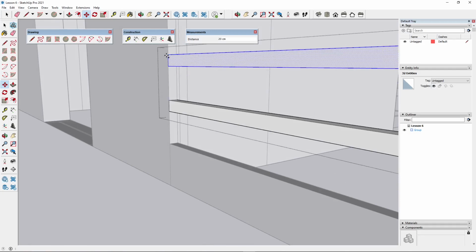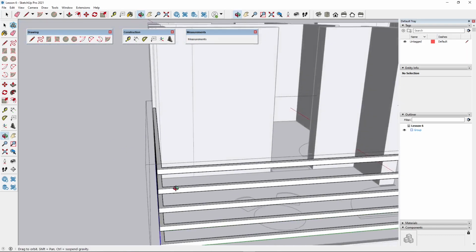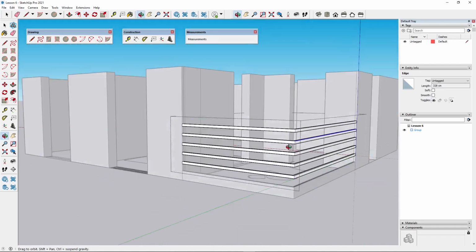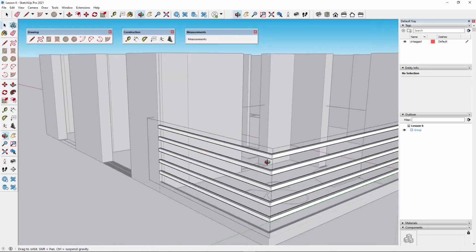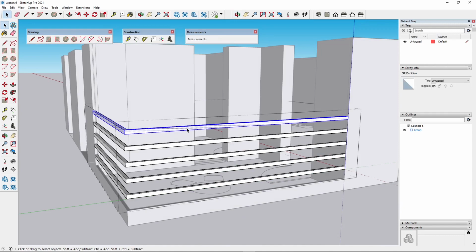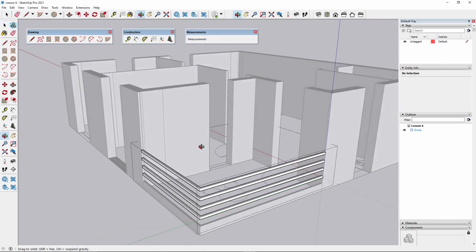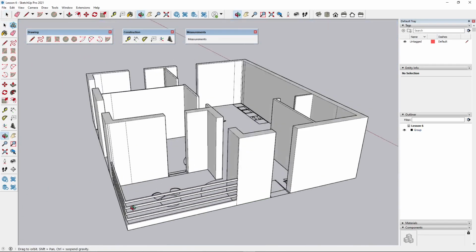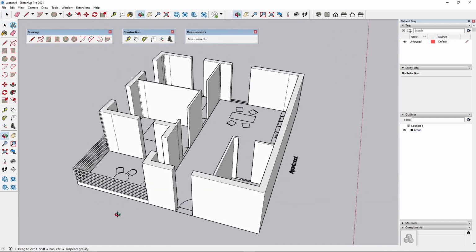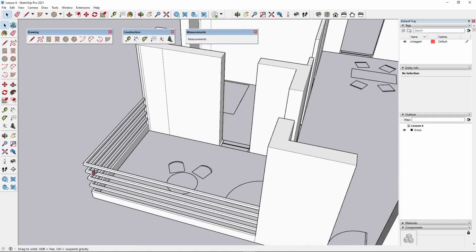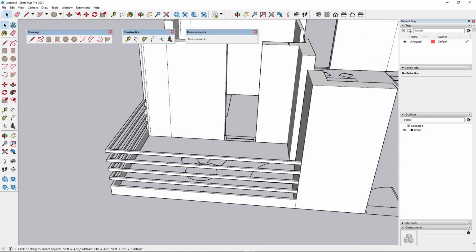Okay, and then click. And then to create more copies, I need to type, for example, 4, if I want 4 copies, and then X. So it's 4 times, and press enter. And this is going to create the other railings here, and maybe I don't want the last one, so 3 clicks and delete. Okay, and then we can go out. So you can see how easily you can multiply and make multiple copies of your objects here.